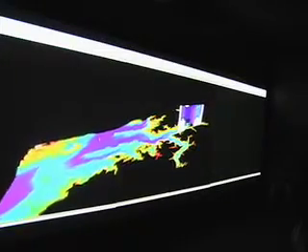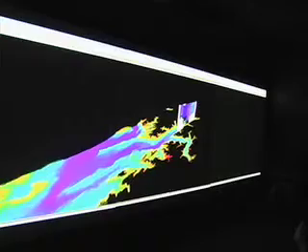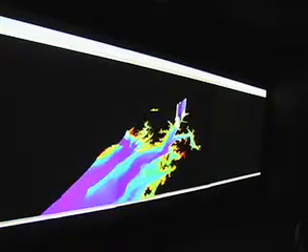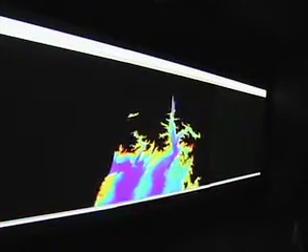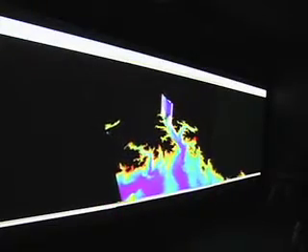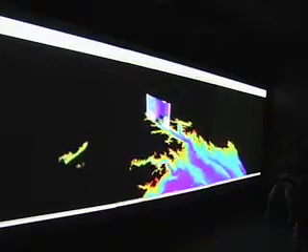This is turbidity for June 28th. Again, cool colors represent low turbidities. Turbidity is the amount of suspended sediment in the water column, or how cloudy the water is. You can see this ranges from about 0 to 10. The river really does not get that turbid, especially in times of drought. You can see some kind of maximum here, but the difference between this is 0 and that's 10, so it's not much of a difference in suspended sediment concentration.